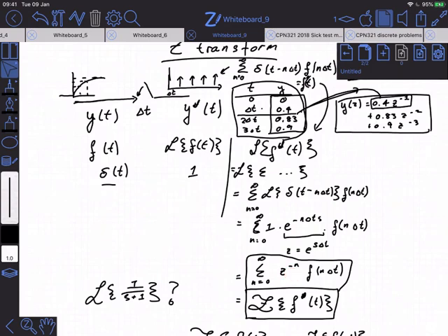Okay? And while we're looking at these formulae, I want you to also think about another interpretation of Z, which is that Z effectively is a shift operator. In other words, if we were thinking of Z being a transfer function, right? If Z weren't part of the signal, but rather something that operated on the signal, we would say that Z to the minus 1 would have the property of delaying the input signal by one time step. Is that clear to everybody?